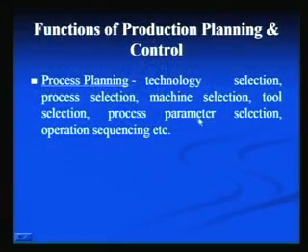Now, when we go for process parameter selection, there are several approaches which are used. One of them is the database approach. That means we try to use some machinability data handbooks and retrieve some of the data from those books to arrive at suitable machining parameters, process parameters. Another approach is the optimization approach, where we try to make a mathematical model of the process itself, and then by applying some constraints and by defining an objective function, we try to determine the optimal set of machining parameters.